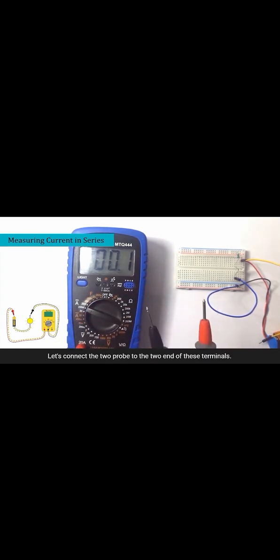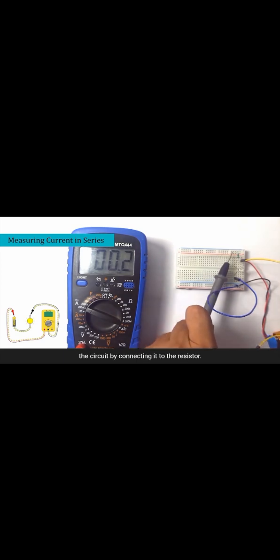Let's connect the two probes to the two ends of this terminal. The first, red color, the positive goes to the positive, and the negative will complete the circuit by connecting it to the resistor. The LED started glowing. It is having 0.7 milliampere of current.